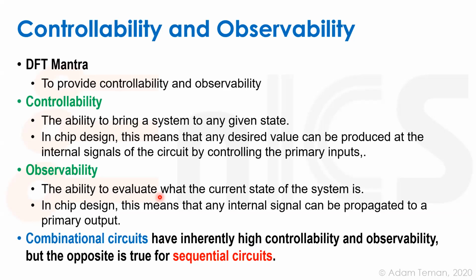But when we have sequential circuits, it is very untrue. And for many years, they tried to develop all kinds of ways of actually making sequential circuits controllable and observable. That's kind of what Udi was saying, that we try to do all kinds of ad hoc types of design that will inherently make us able to test our circuit without doing all kinds of other things. But it's really, really complex and has very low coverage. And that's why basically when what we know as design for test or scan insertion was invented, it's what basically everybody does, even though it has a huge overhead.